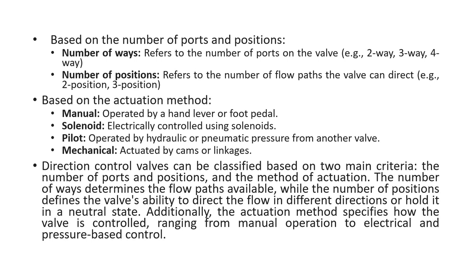These two ports are there, and one is a pressure line, because from the pump the pressurized oil is coming to the DCV, and T is a tank, to which the return oil from B is returned. According to position, this is the forward motion. When we require reverse motion, the direction control valve spool operates, then P is connected to B and A is connected to tank.